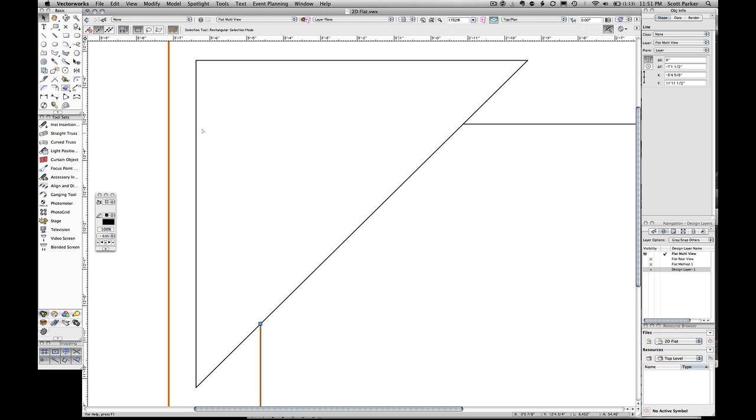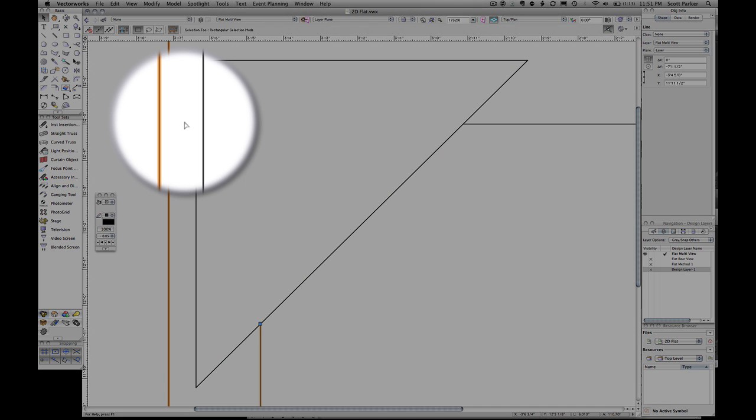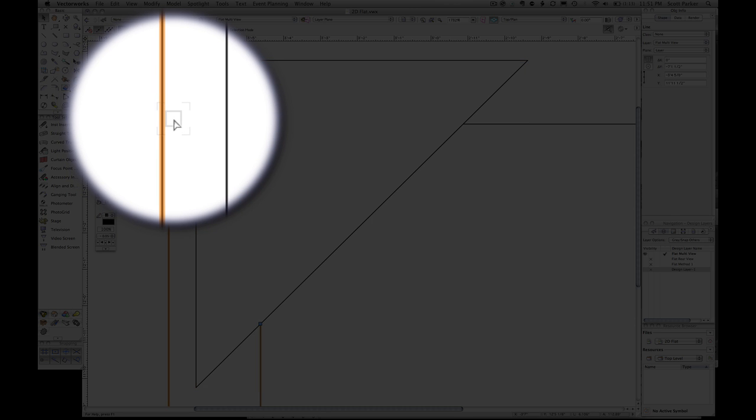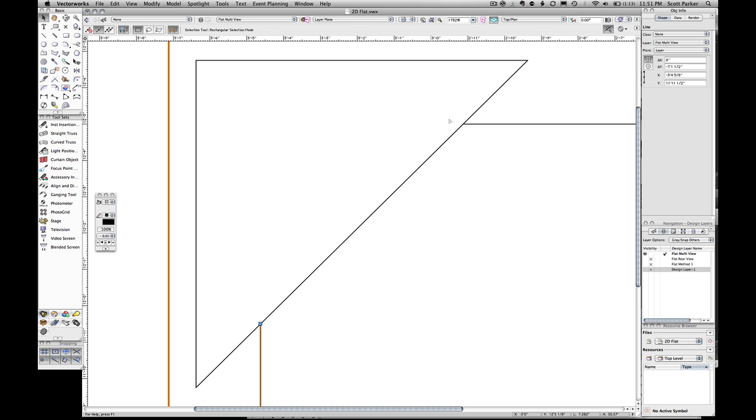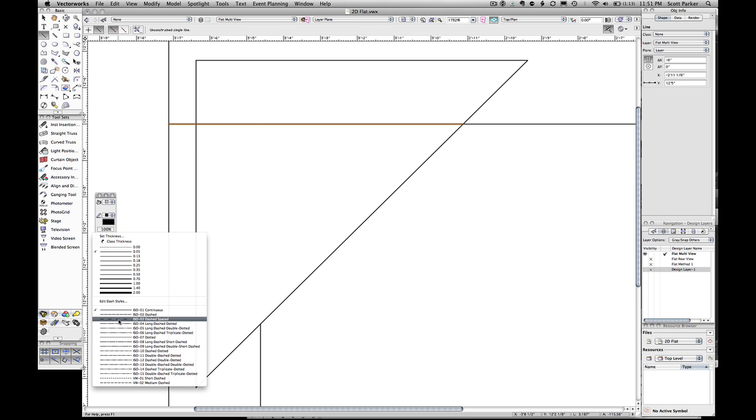However, now it looks a little bit empty, especially over here at this side, because the line should, in theory, continue. So we're going to put in what's called a dashed line. We would see a dashed line in technical drawings that allow you to indicate where an object is behind another object. So I'm going to draw an independent line, replacing that section of line that we just used, and I'm going to assign it a dashed line, just like so.